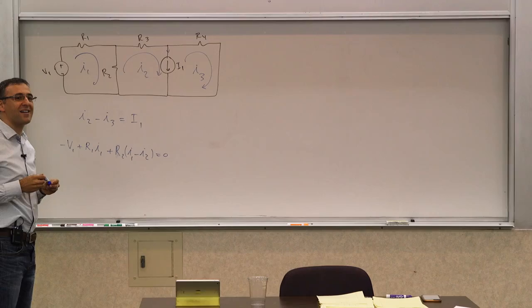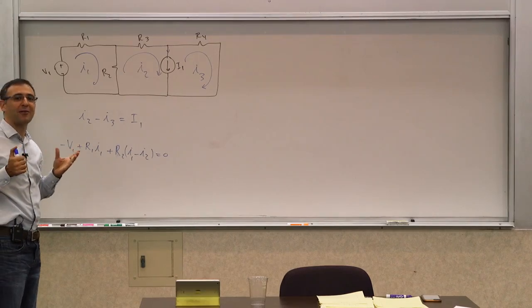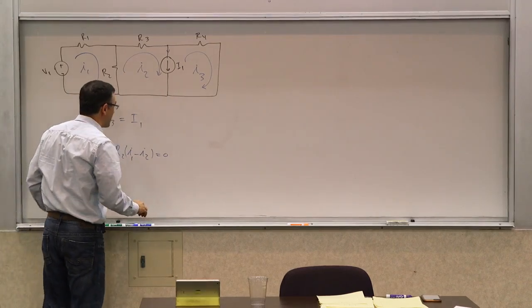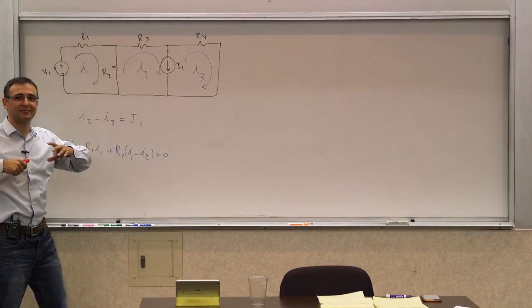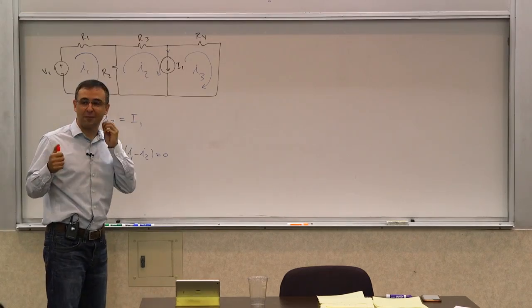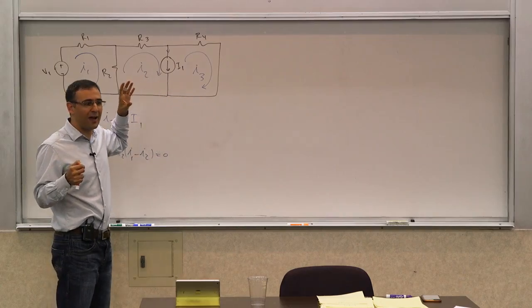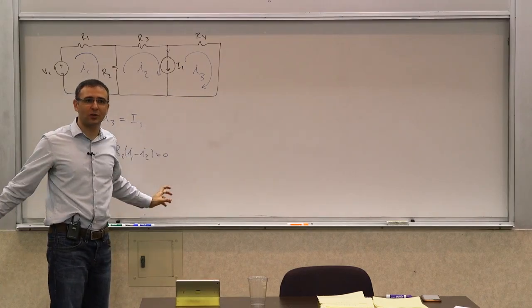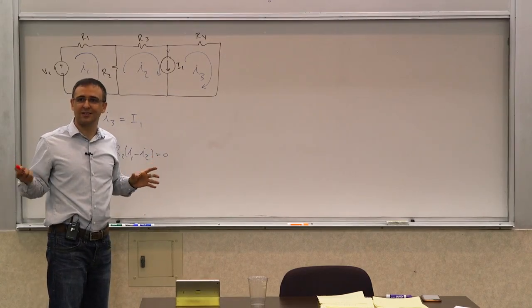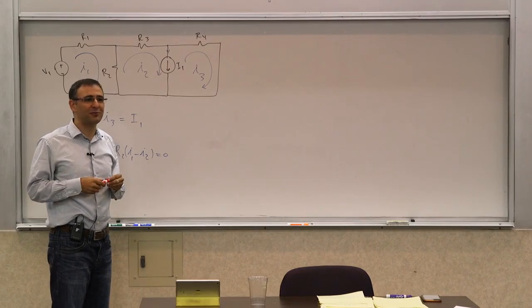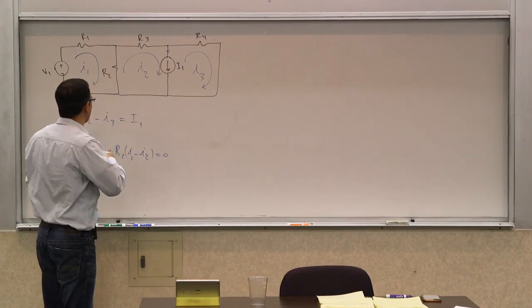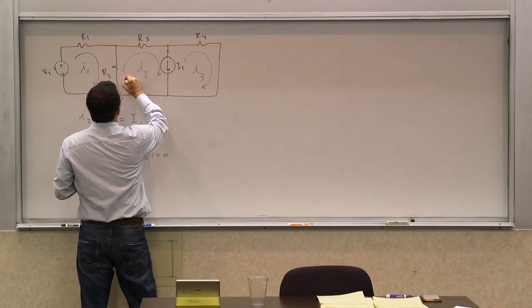So what do I need to define now? Use your powers of extrapolation. We had something that you needed to get rid of. In the case of nodal analysis, it was where you had a current source and you absorbed it into a supernode, so it didn't matter. So what do you need to define? Super mesh. Yes. To the rescue.